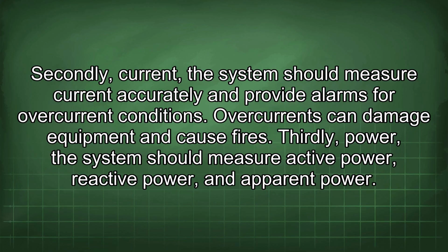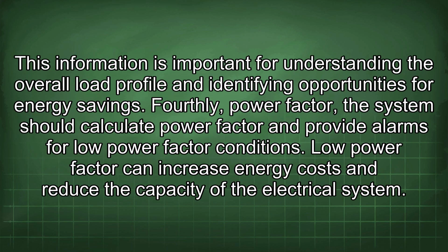Thirdly, power. The system should measure active power, reactive power, and apparent power. This information is important for understanding the overall load profile and identifying opportunities for energy savings. Fourthly, power factor. The system should calculate power factor and provide alarms for low power factor conditions.